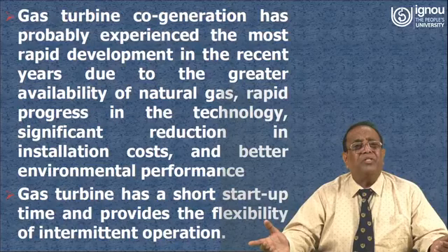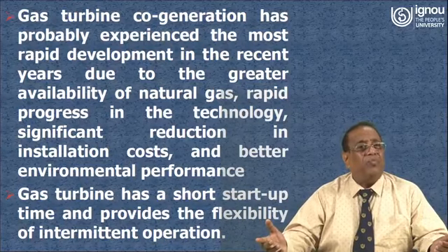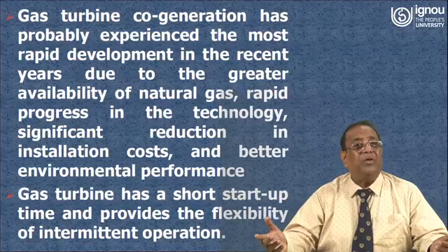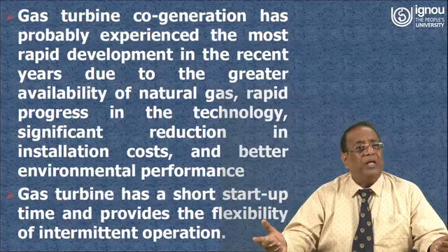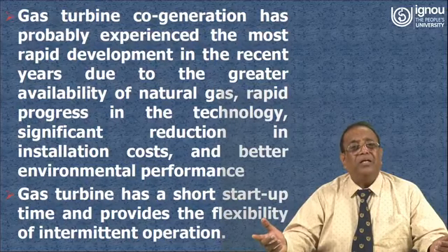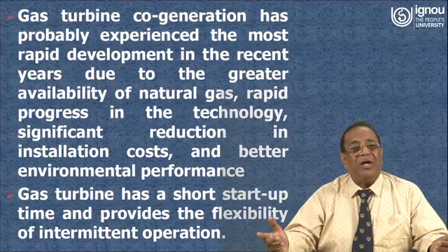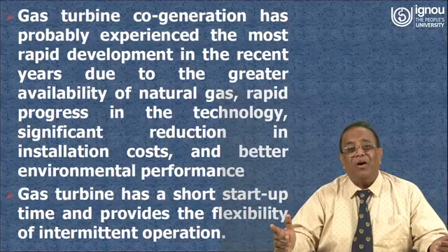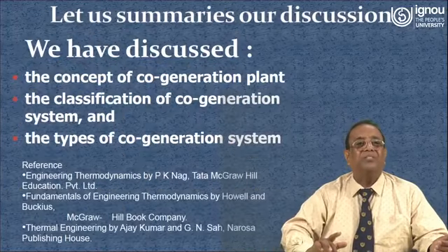Gas turbine cogeneration has probably experienced the most rapid development in recent years due to the greater availability of natural gas, rapid progress in the technology, significant reductions in installation cost, and better environmental performance. The gas turbine has a short startup time and provides the flexibility of intermittent operations.